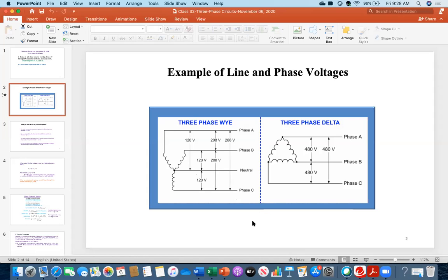Now the problem is that, for example, you are talking through phone to someone long distance or an overseas international call. Sometimes you might see interference or too much noise on the line, or you are not making the calls at all because of that interference through the neutral line. Because in the overhead lines, the power lines and the telephone line share the same neutral line just to save the conductor cost. That is the other problem.